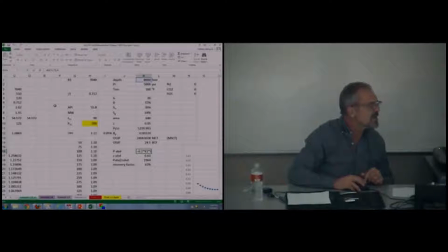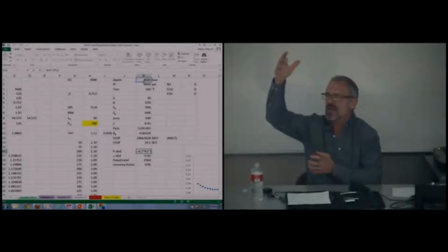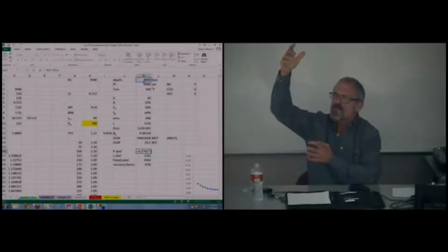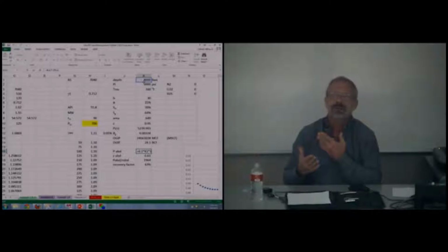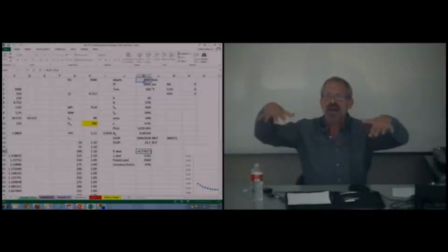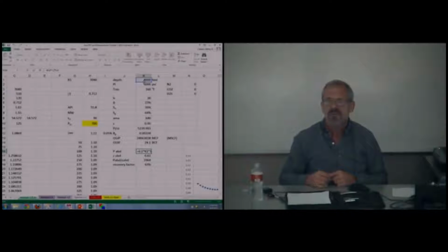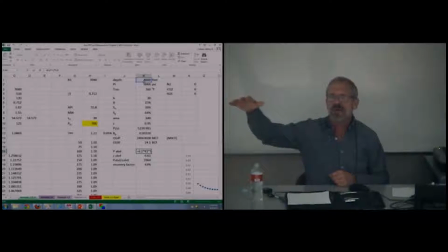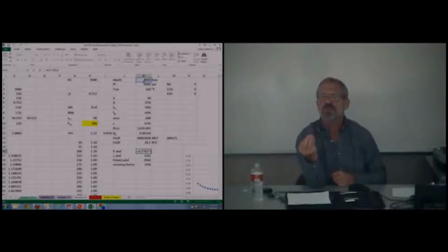Here's my equation up here. I bumped it, 0.1 times 8,000 is my gas gradient. With no rate at all and no friction, then I'm guessing what my bottom hole flowing pressure is. But that's not my abandonment reservoir pressure because there's this cone and I have to accommodate for that. So that's why I bumped it by 50%. I'm saying that a lot of my reservoirs got higher pressure than that. That's the lowest point in my pressure.